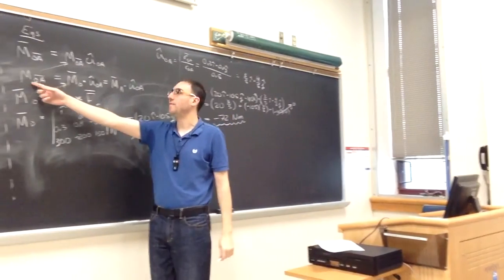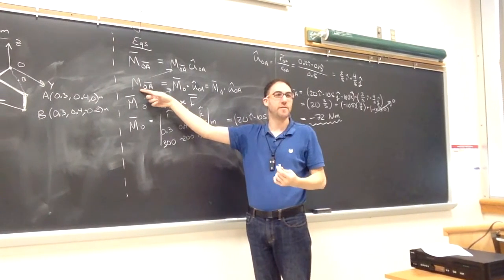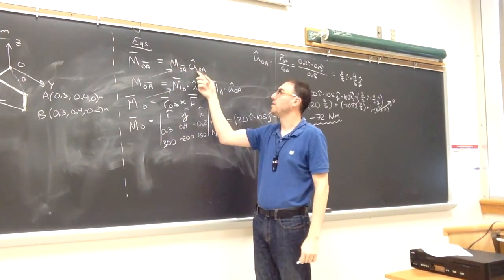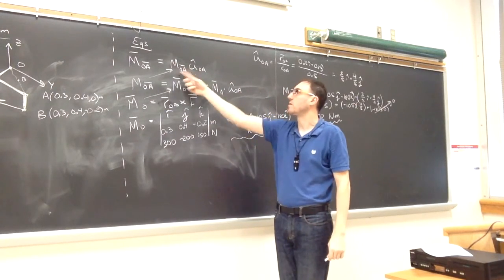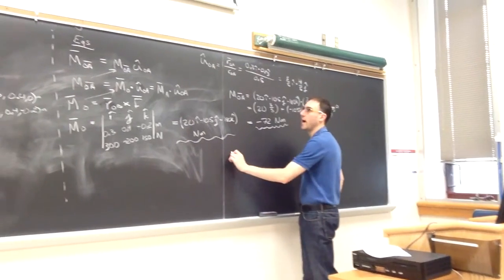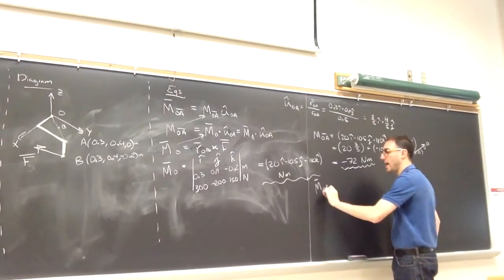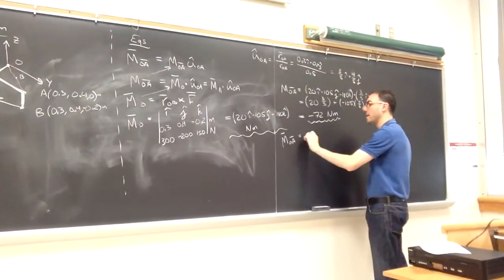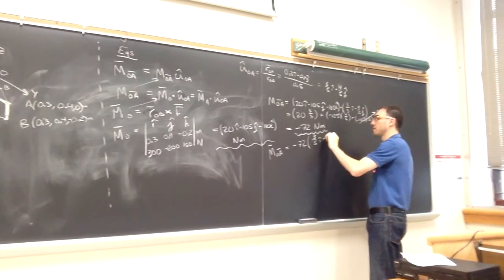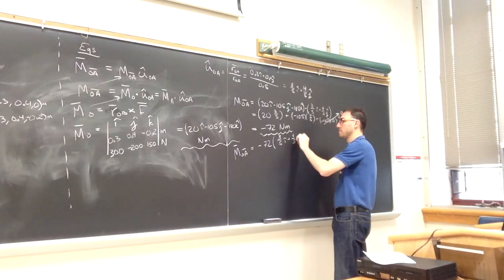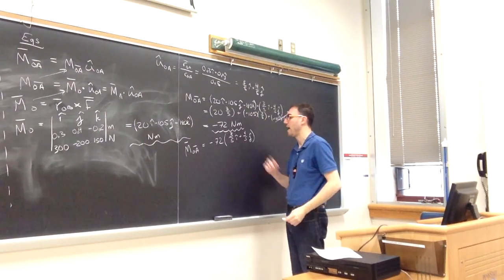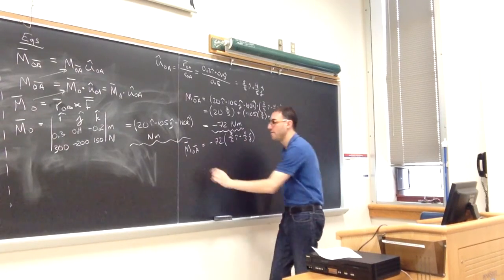We now have the magnitude of the moment around axis OA. So now we take that result and multiply that scalar times the unit vector that we found before. So finally, the moment as a vector will be negative 72 times 3/5 i plus 4/5 j. Like we did in section 2, I can distribute that scalar value into my unit vector.